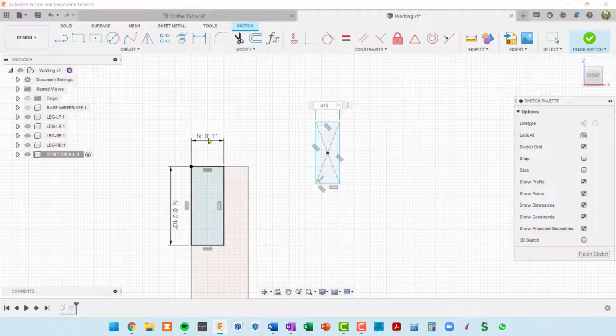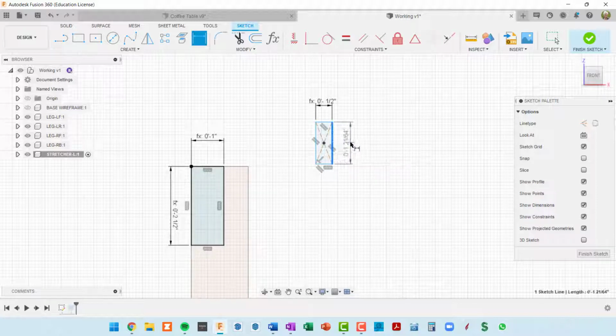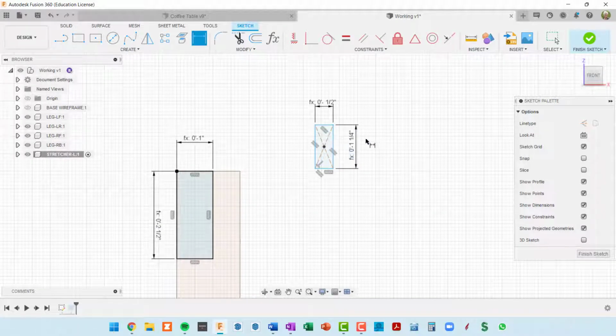Click there, and then divide that by 2. That's actually the apron depth divided by 2. And this one's going to be our apron height. I'm still in my dimension mode, so I pull a dimension off of here, click, come over to this dimension, and then type in /2. Okay, so now I've defined this rectangle.